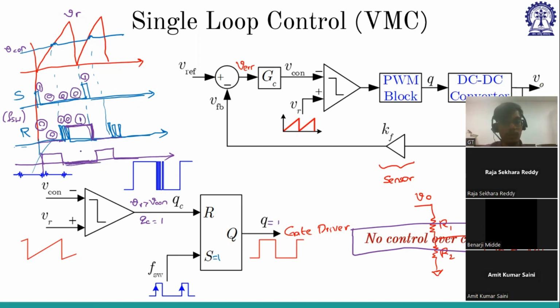Sir, could you please elaborate here? When the reset R is 0, then the output will be set 1. Okay. Then 0, 0 memory state, it will be 1. See, when set is 1, reset is 0, so output will be set to 1. And now set has become 0 and reset has become 0. So it will retain the previous value, which is 1.